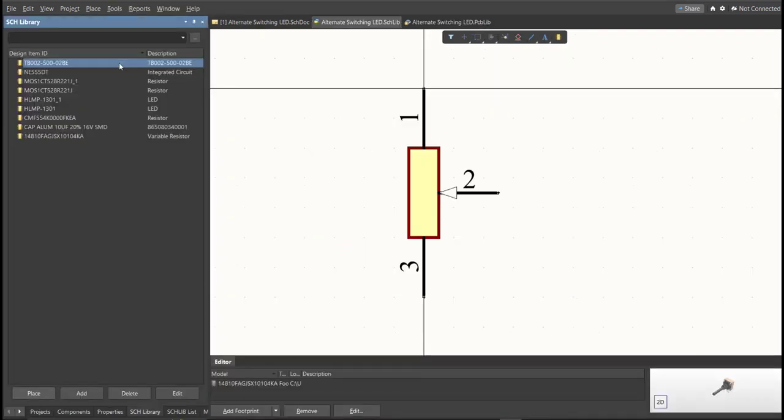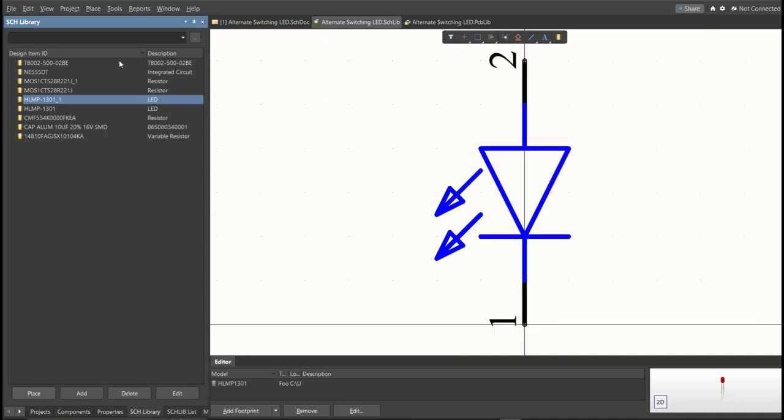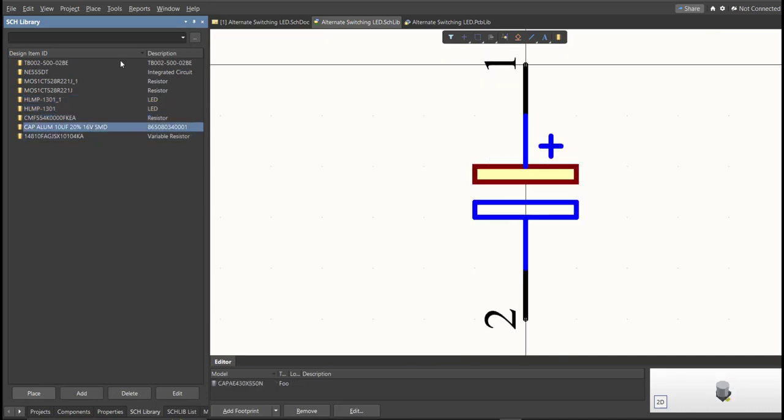After you finish all the components in the BOM list using a library loader, you can check here in the schematic library panel all the added libraries. So these are the added libraries for this PCB. Next, we're going to put all of this in our schematic doc.